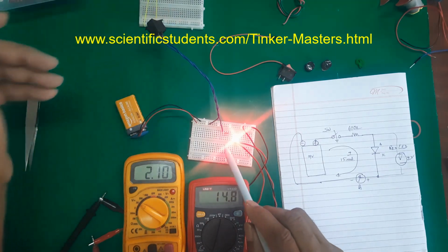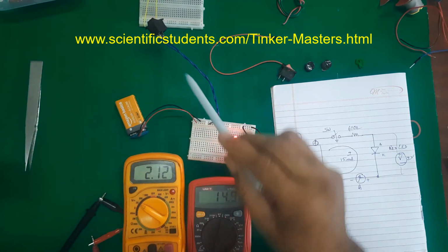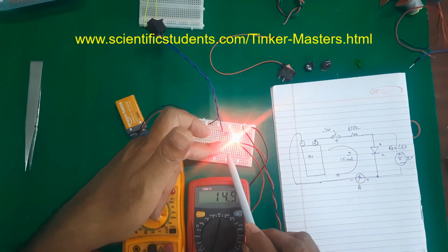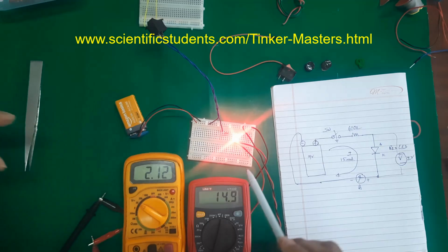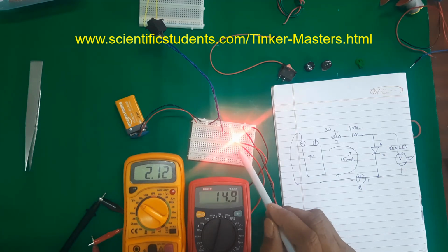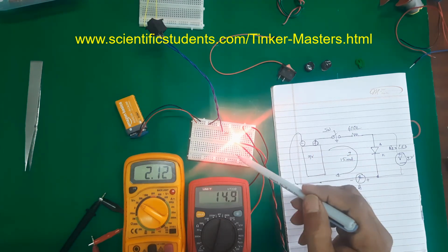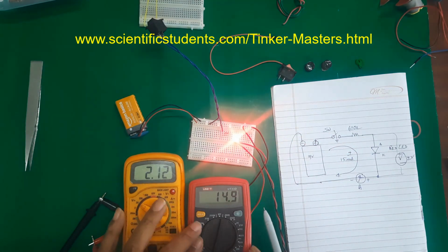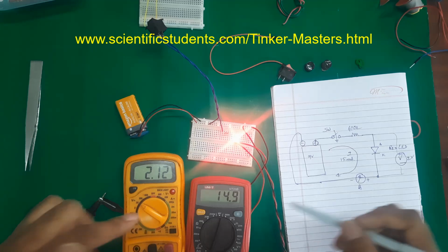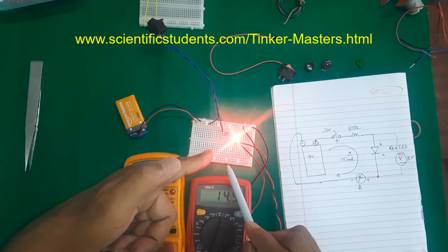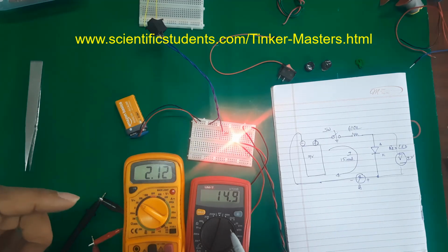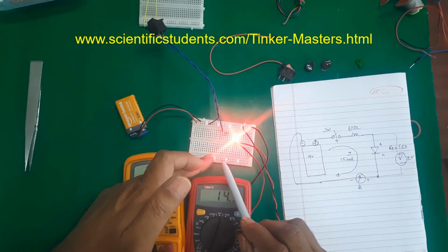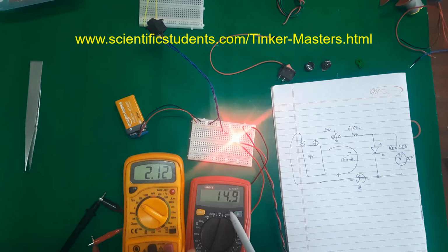You see now. The 9 volt went into the switch and returned back, and then it is going to the resistor, and from the resistor it is going to the anode of the LED. The cathode of the LED is not directly connected to the negative of the battery, because I wanted to show you how much current the LED is presently pulling because of the value of the resistor we have used here. It is 470 ohms at this point of time. So 9 volt influenced by the 470, the current required for the LED is 15 milliampere.